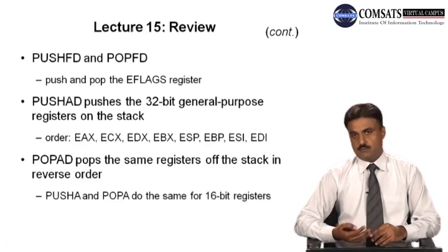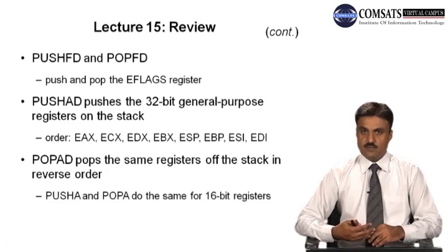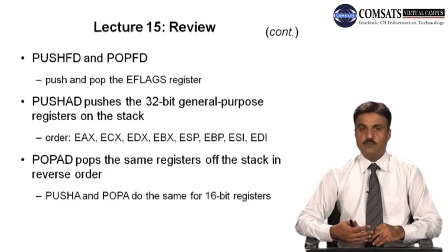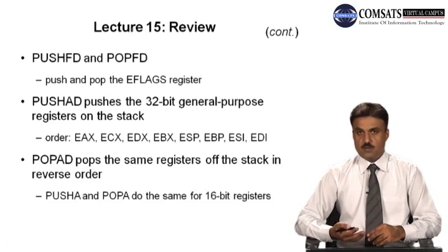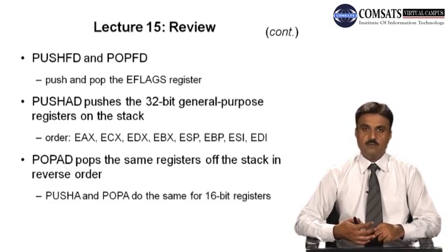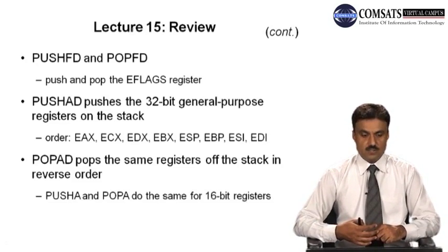If we transfer control somewhere else, then before transferring control we first push the values of the registers along with their flag status. Then we perform some other operations, and when we return back, we continue the normal execution.